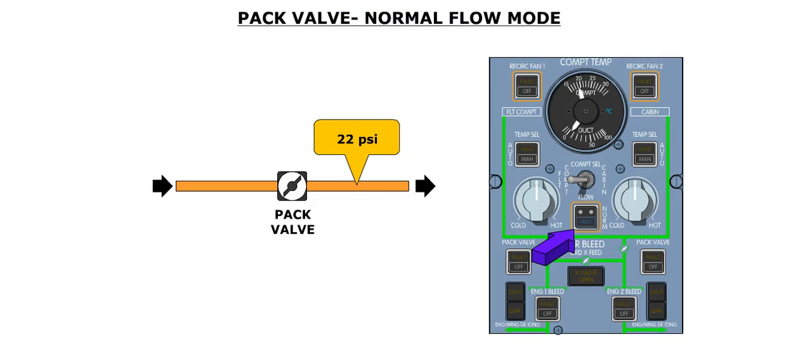The flow push button controls the amount of pressure that is regulated by the pack valves. In the normal released out position, both pack valves will regulate pressure to 22 psi. In the pressed-in position, the flow push button will cause both pack valves to regulate pneumatic air pressure into the packs to 30 psi. The increase in pressure results in an increase of flow out of the pack. The cyan high caption illuminates in the push button when it is pressed in.